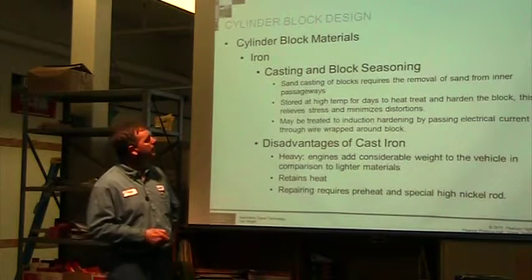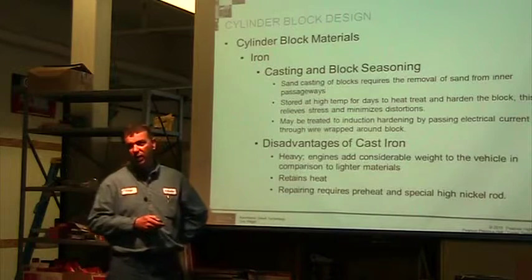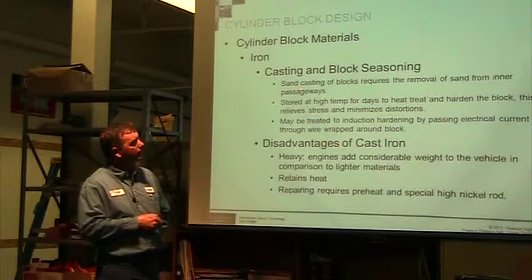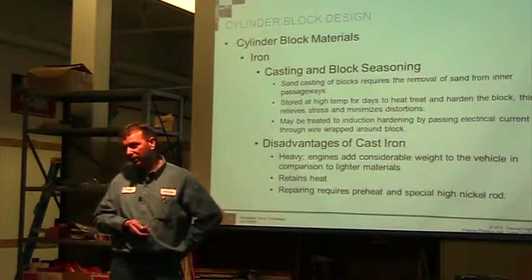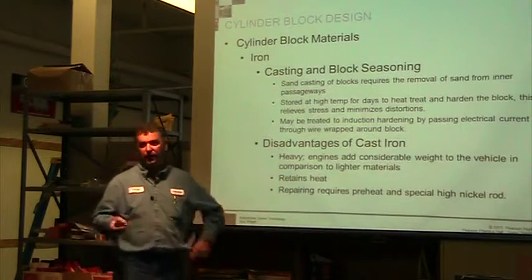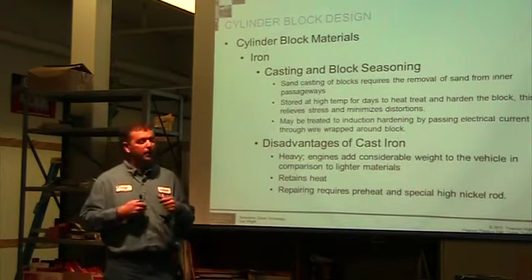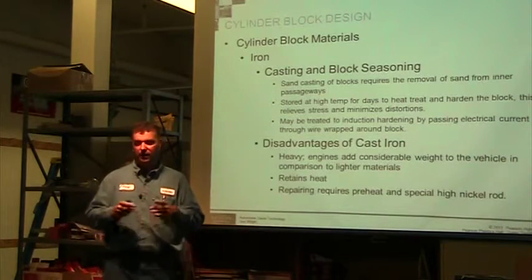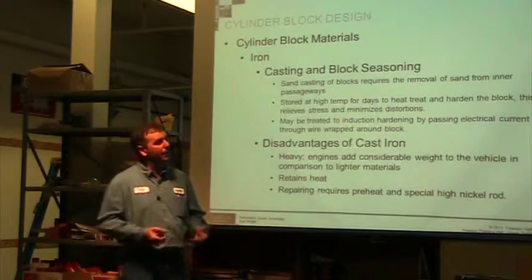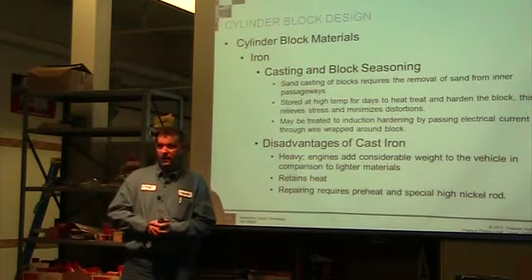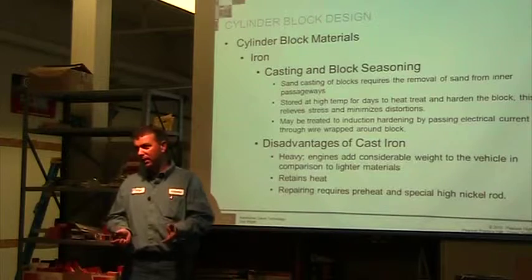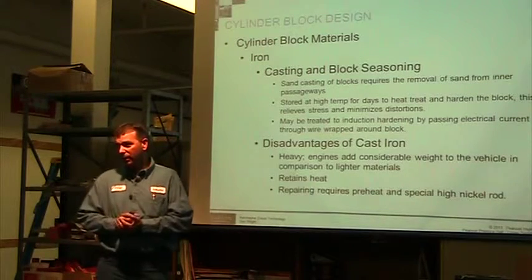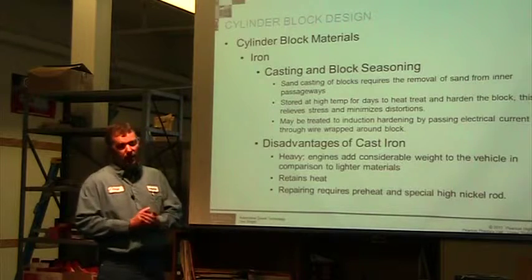Cylinder blocks, cast iron or iron, is the most common. So some type of cast iron. They use sand casting. Somehow you've got to remove the sand if you're going to use sand, so they have soft plugs. We look at soft plugs as a way, when the engine freezes and you leave water in it, the soft plugs pop out. It's kind of an added safety feature: if you're lucky, it just pops the soft plugs out and the water drains out. If you're not lucky, it just breaks the block.